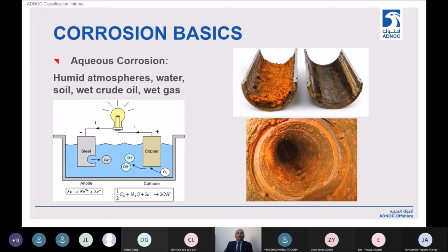Here is an example of internal corrosion again. As you see, pipe or pipeline materials tend to carry fluids. I mean, they're designed to carry fluids. In the oil and gas business, it's either oil, gas, water, or a combination of the three, which we call multi-phase fluids. You can have deposition of brine-based scaling products, or you can have deposition of bacterial microbiological growth, which results in slimes and deposits of bacteria which thicken over time and cause under-deposit microbiological corrosion.